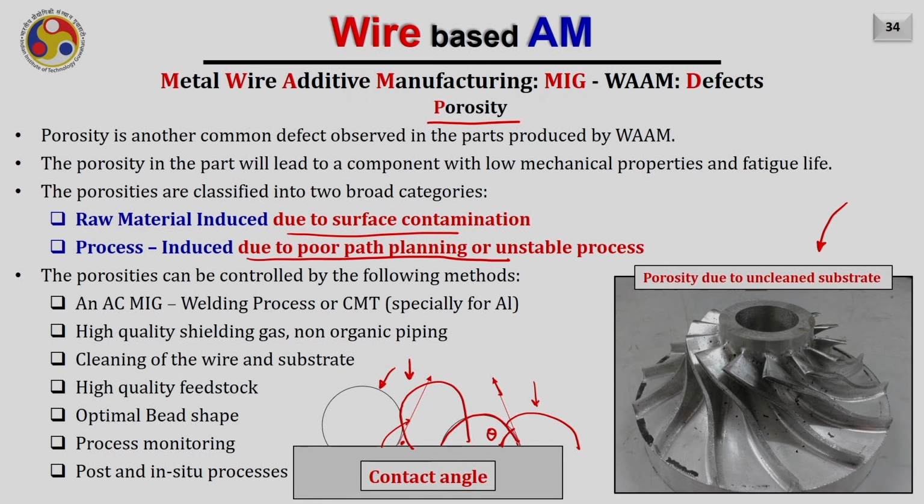So, what I did when I was depositing the material by using wire arc additive manufacturing, I was machining it as well, and while doing the machining I used coolant, and that coolant used to have organic components in it. When we deposit the next material, those organic components produce some gases, which escape and leave porosity behind. That is why whenever we perform any wire arc additive manufacturing operation on any surface or pre-built layer, make sure that it is clean enough and free from any contaminations.